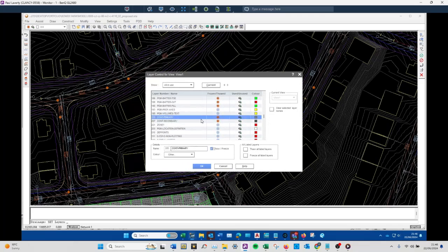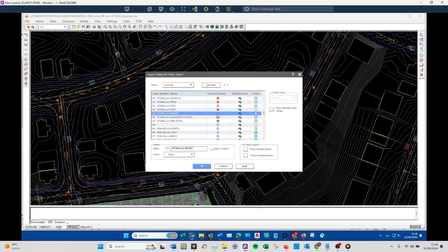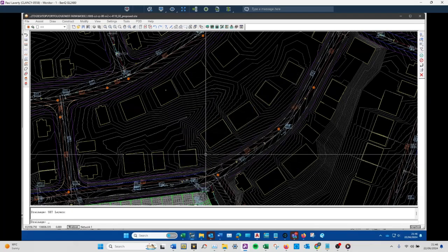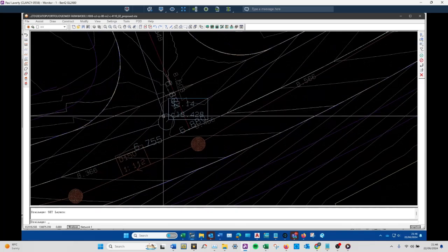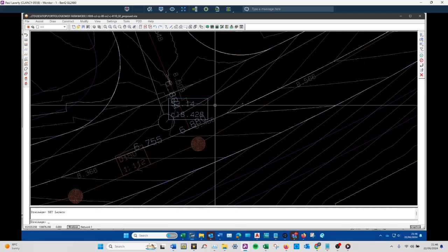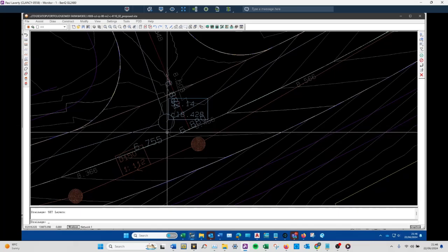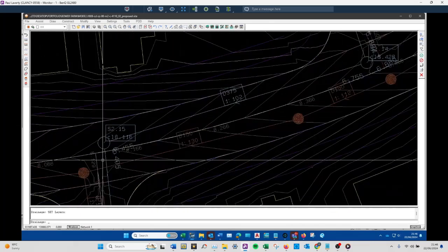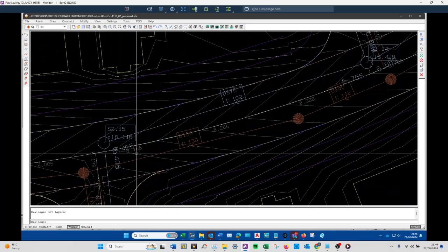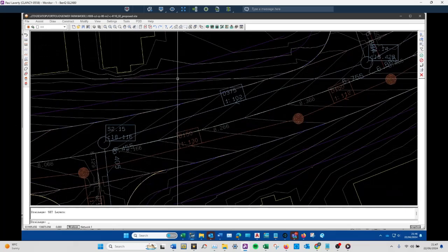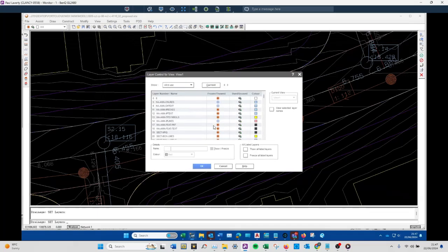I need to adjust the line work for it, flatten it out, and then regenerate your ground model, and then update your cover levels of your PDS file. So you're going back and forth between the two, and it happens quite a lot as you refine that design. I mean, it should happen quite a bit, because if you're not, then you're not really refining your design to the optimal design. You're just doing something that looks kind of right and you're just spitting it out.